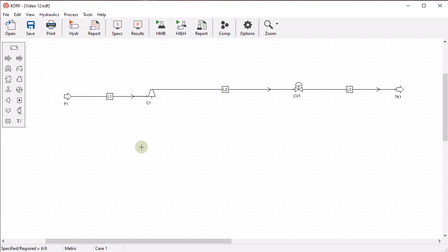As per design guidelines, any control valve on gas service must have at least 40 kilopascals pressure drop. To model this system, we need a compressor, a control valve, one feed, and one product. We will also need specific components for the mixture.